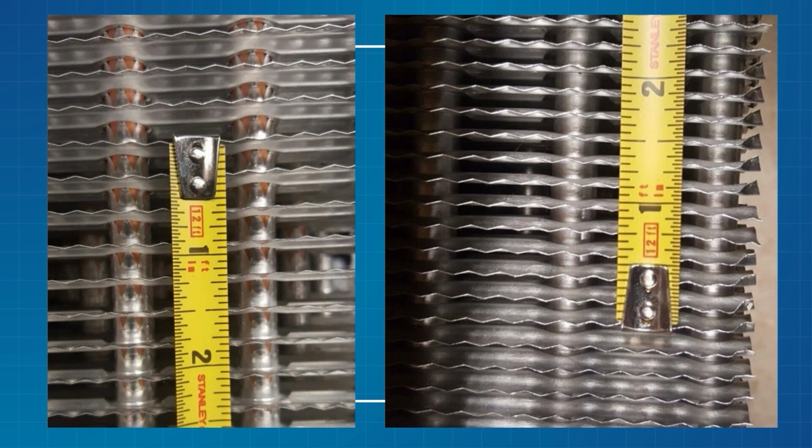If I have, like on this left picture, frost on this fin and frost on this fin, I must have a gap big enough for air to also flow. When the frost touches and I stop my airflow, that is what we call an iced up coil, and that's a service call. My case is running warm because I'm not moving any air, right? So the tighter the fins per inch I get, the less room for that frost I have. All right? So this is a balance. It's a very, very delicate balance for refrigeration, extremely delicate.